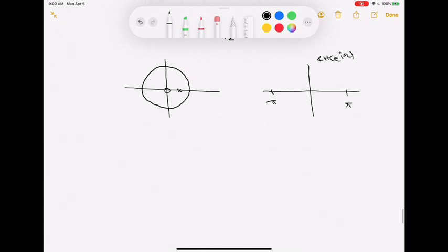I'm going to look at the angle response first at H(e^{j0}). This is the DC angle. As long as it's a real system, I'd expect it to be one of two things. You can have a DC come through positive, or it might be negated, so that's a phase of either 0 or pi.